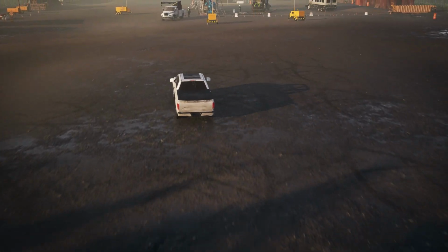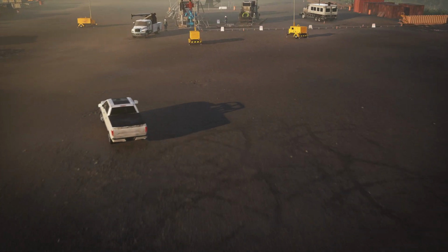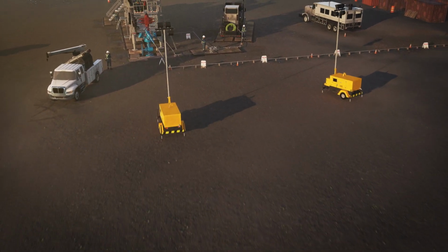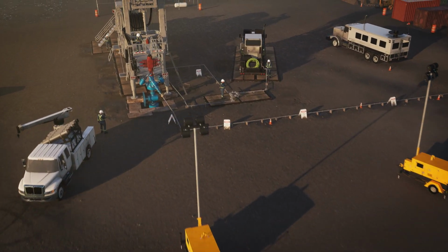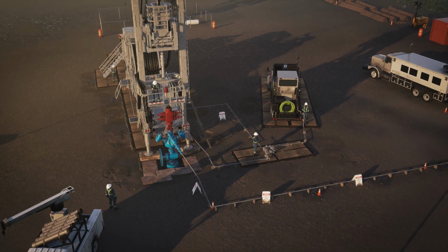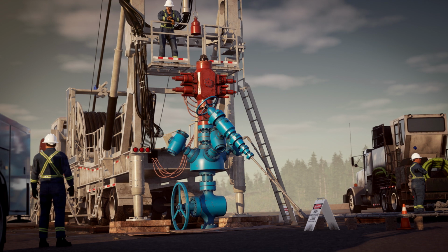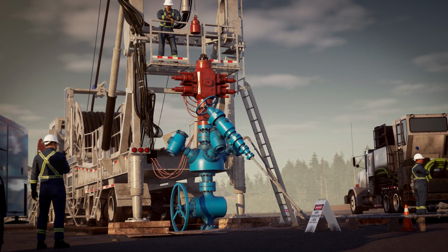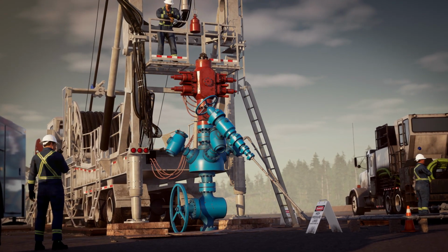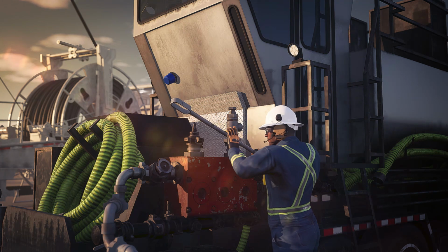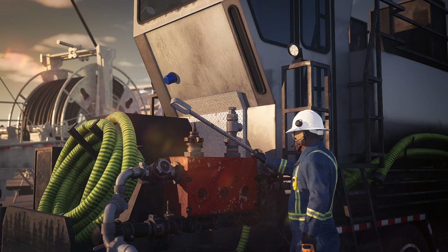It was early on a warm summer morning on August 3rd, 2017, near Veteran, Alberta. The day crew on a coiled tubing rig were preparing the BOP for fracking. Unknown to the day crew, pressure remained in the BOP and piping from pressure testing the night before. The pumper operator opened the valve on the pumper to direct any water pressure to the tank on the pumper truck.